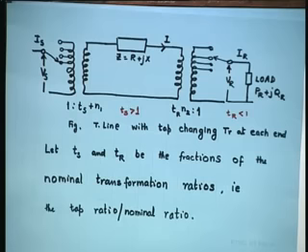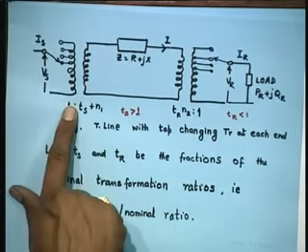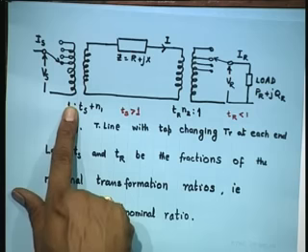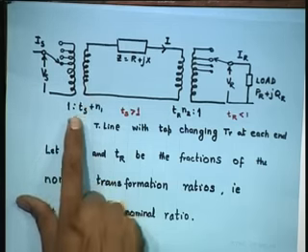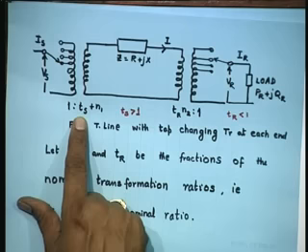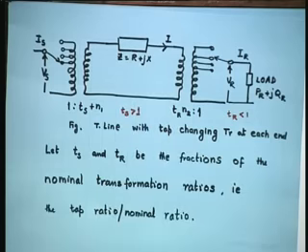Now, you can do it either manually or automatically. Now, this is the circuit diagram or schematic diagram for transformer control, which I explained to you briefly. It is a big diagram here. This is Vs, Is, this is the sending end transformer, which is step up because the generator kV is lower and the transmission line needs higher. So, it is 1:Ts N1. N1 is the original number of turns, Ts is the sending end taps. Then this is R plus jX, assuming that it is a short line.